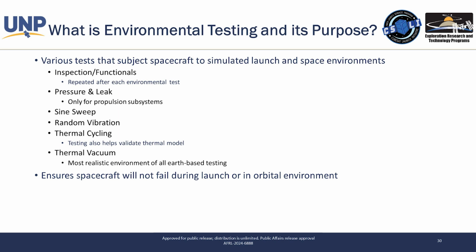So we do both vibration testing and thermal cycling. As you go through day-night cycles in orbit, you cycle the temperature quite dramatically. And then obviously you have to exist in vacuum forever. We can use a chamber to simulate both the vacuum and the thermal environment.